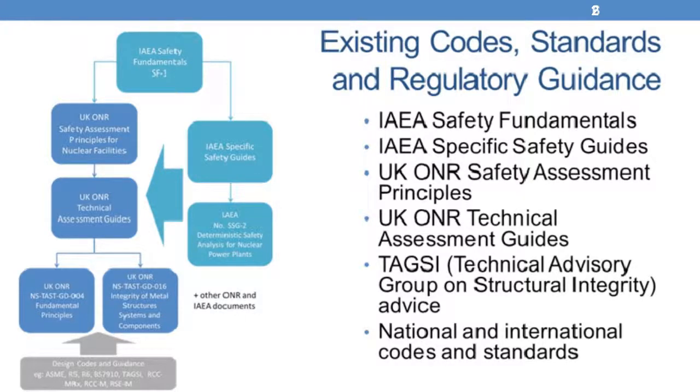I should highlight that this guidance doesn't actually rule out or prevent probabilistic structural analysis per se, and indeed it is integral to the analysis of AGR graphite, but the majority of probabilistic commentary relates more to thermal hydraulic analysis. So one of the aims of the working group is to demonstrate with worked examples the benefits and limitations of application of probabilistic type approaches to structural integrity analysis.